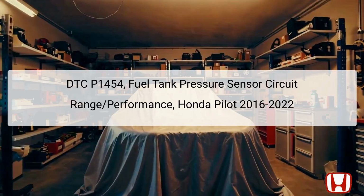The Diagnostic Trouble Code, DTC P1454, indicates a fuel tank pressure, FTP, sensor circuit range performance problem. This sensor monitors the pressure inside the fuel tank, providing vital data to the vehicle's powertrain control module, PCM, to manage fuel vapor emissions effectively. When this sensor fails or its circuit exhibits abnormalities, the PCM will detect these irregularities and set the P1454 code, which can affect vehicle emissions and performance.